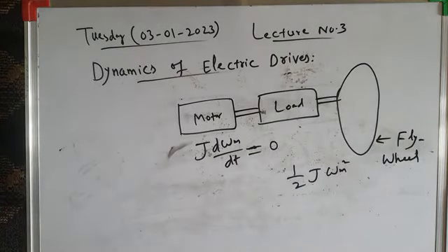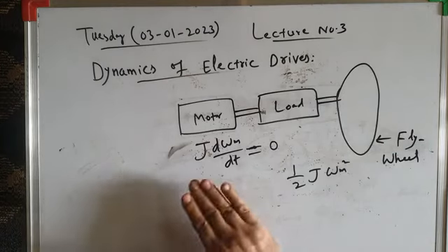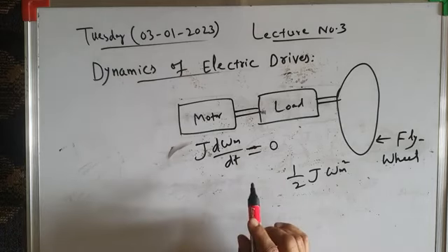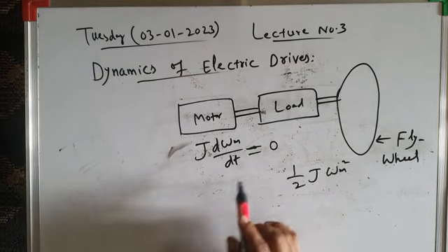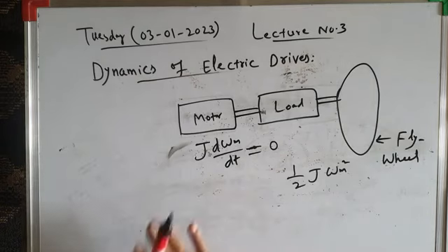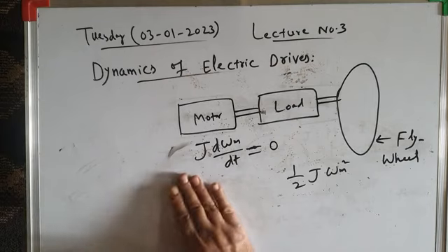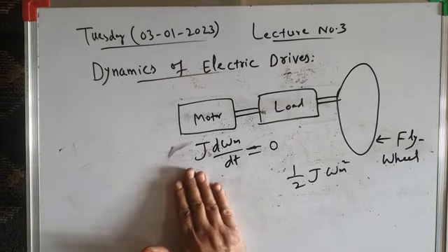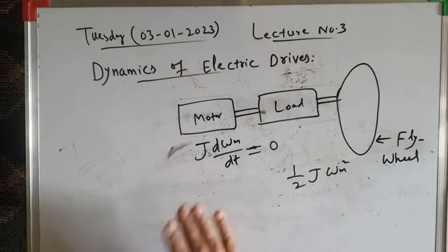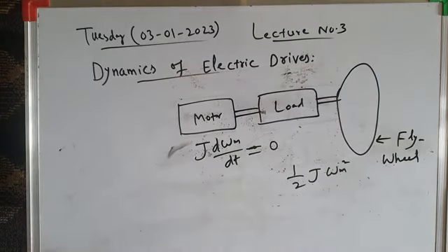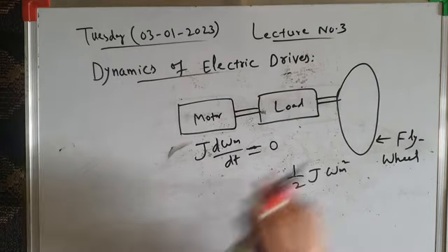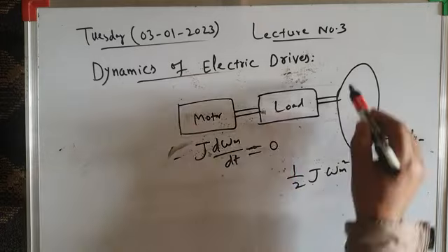Now let us suppose the pressing process takes place. The machine presses. It moves down and it makes a press. When this pressing phenomenon takes place, what happens to the motor? The motor applies torque, because for the pressing phenomenon a certain amount of torque is required. So it applies the torque for doing the pressing, and simultaneously the motor, while doing this pressing process, decelerates. And when it decelerates, what happens to this inertial torque?